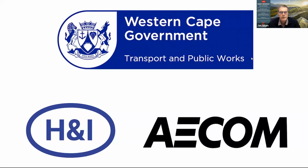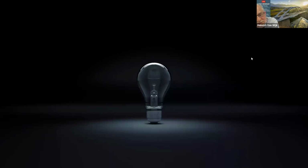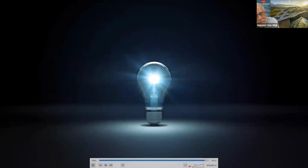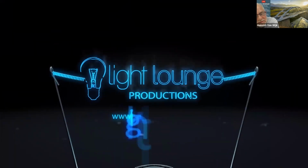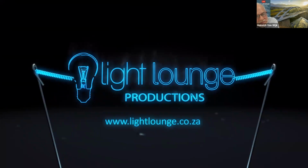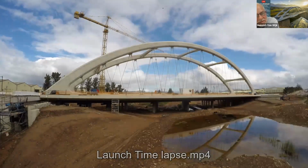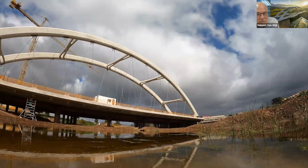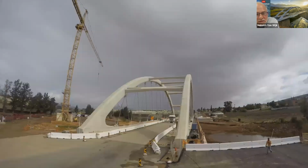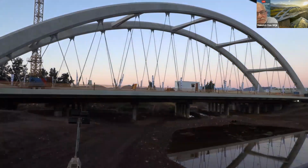Yeah, okay, thanks. Maybe I can just add, due to the construction process, there was quite a delay between the stage 2 and stage 4 tensioning, because the stage 3 we did with the bridge in its original position, and stage 4 we did with the bridge in its final position. So that allowed us to monitor displacements and also look very carefully at our time-dependent behavior over that period, bearing in mind that a lot of your creep and shrinkage happens in the first 6 to 12 months.